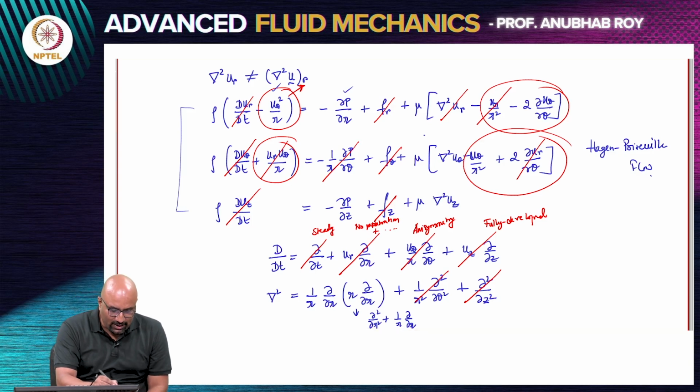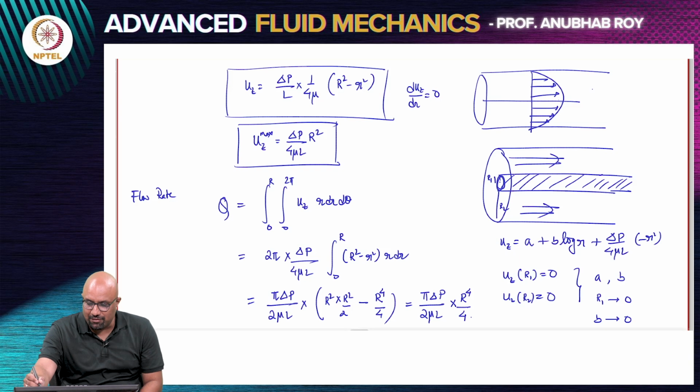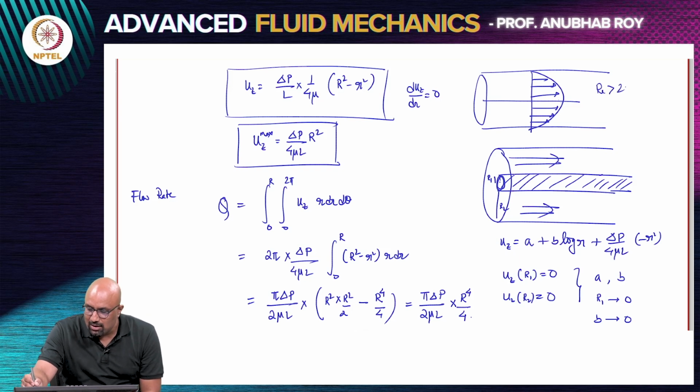Now, this mathematical solution that we have obtained, the Hagen-Poiseuille profile, this parabolic velocity profile, is going to describe reality if your Reynolds number was much lower than 2000. If your Reynolds number is larger than 2000, this particular velocity profile ceases to be stable. It becomes unstable.